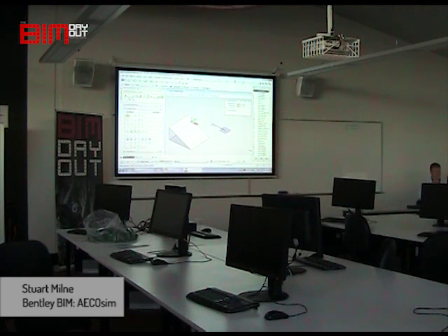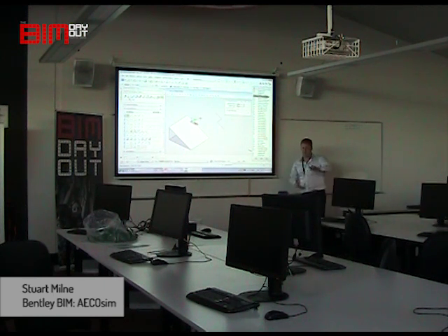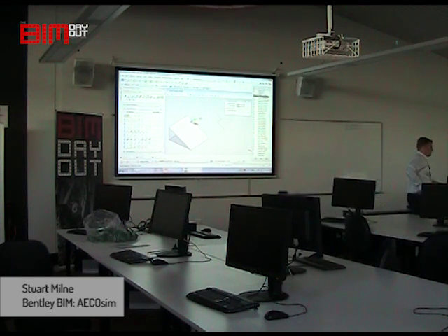Say your existing angle looks like that. Type in RE and click on an object that might be on an angle, and then you see your AccuDraw compass rotate, and you're good to go. So you're basically just creating a drawing plane on the fly using the existing object.